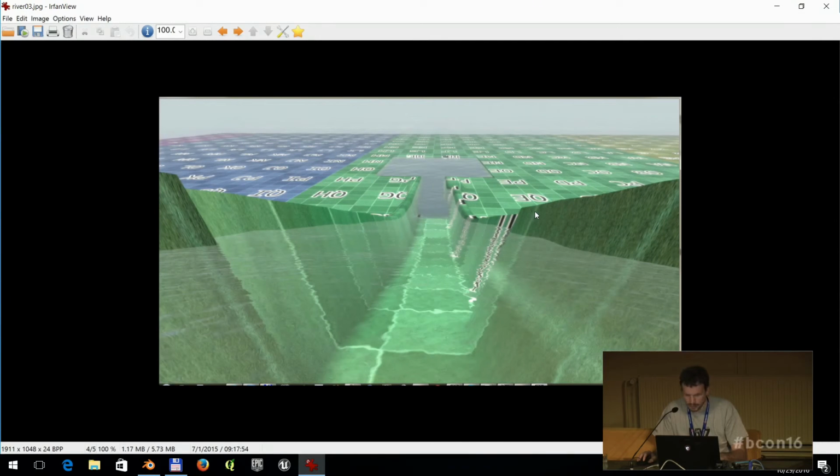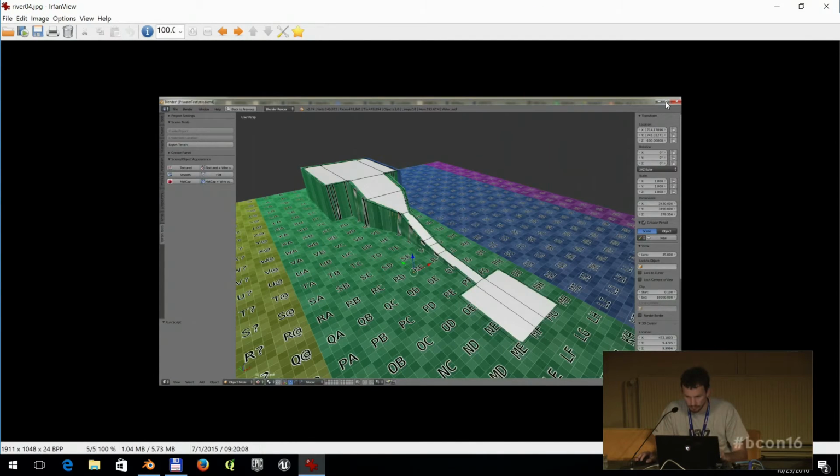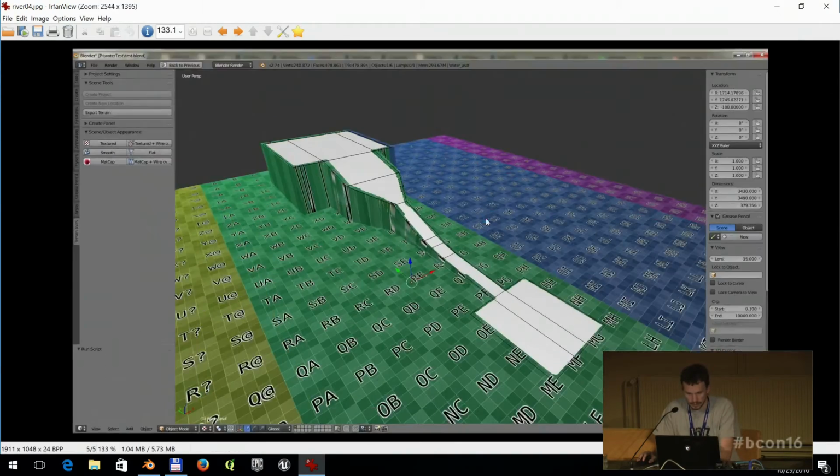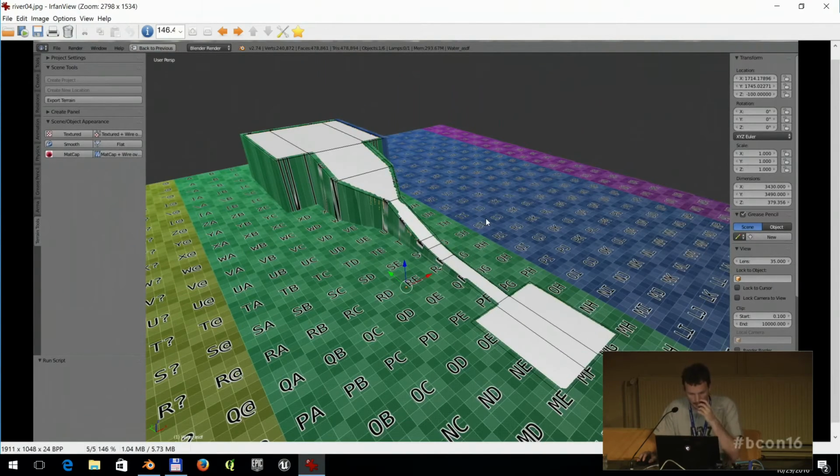It's a nice slide, and it was done really quickly in Blender. I imported the terrain, made a shape of the water, and the other terrain was snapped to this shape with the shrink wrap modifier, and also exported into the engine.